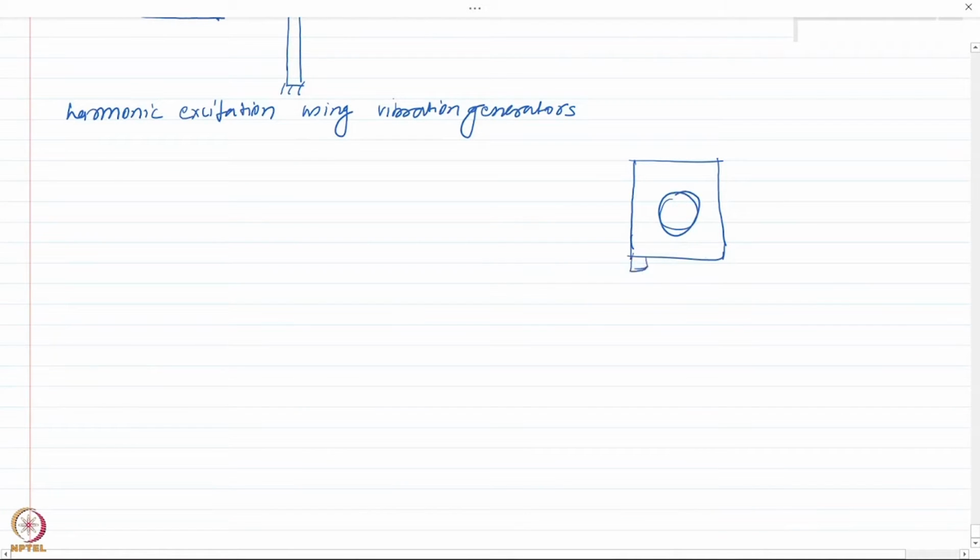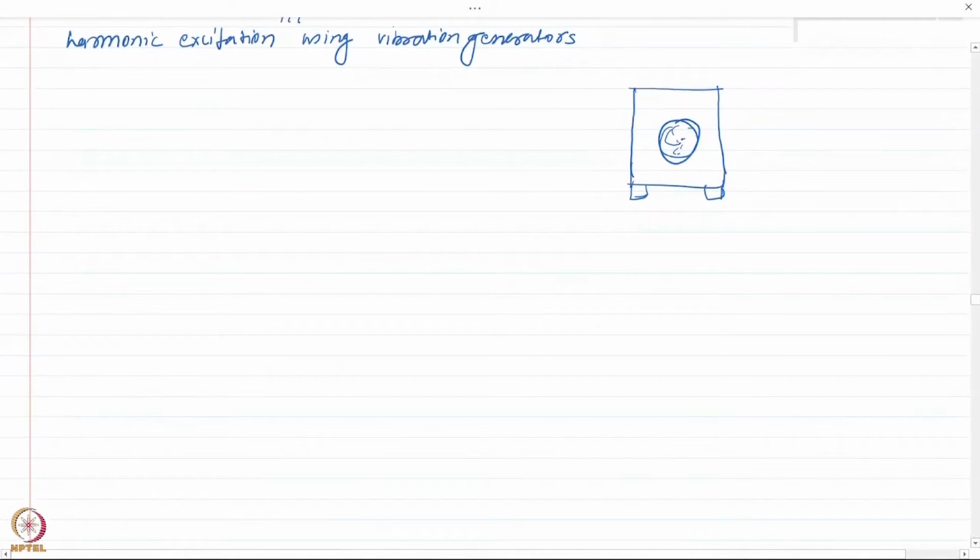Many washing machines now have different technology to balance the load, but usually, due to clothes rotating inside, the mass distribution is not symmetric about the center, and that leads to unbalanced load. Consequently, due to the frequency of the unbalanced load, a load is applied to the supports here, and you can observe that in any common scenario where the washing machine is being operated.